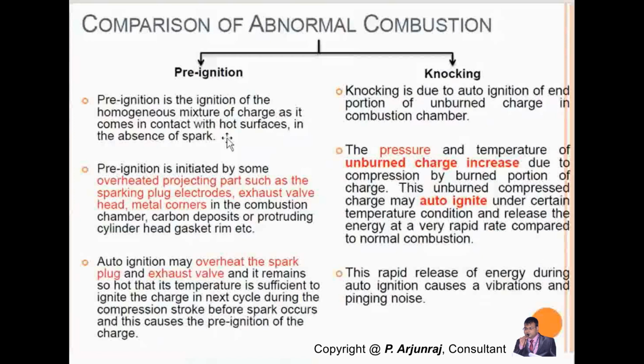before it reaches the end of the compression stroke, before the piston reaches the 20 degrees where the spark normally occurs, ignition happens, and this also causes pre-ignition of the charge. Normal ignition is firing 20 degrees before TDC. So what is the meaning of pre-ignition? When you look at the valve timing diagram, you can see 15 or 20 degrees, whatever it is. Instead of 15 or 20 degrees, if I ignite at 30 or 35 degrees,